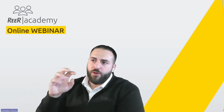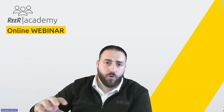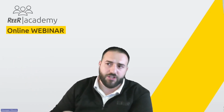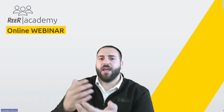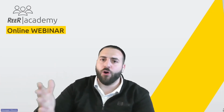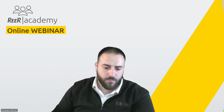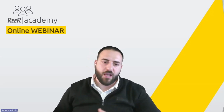So we don't need ProfiSafe because we don't need now to exchange data. Of course, we are planning to work on something that is able to communicate as a Profinet device with a ProfiSafe device at a higher level. But in this case, we cannot say it's the same. We collect all the safety functions into the module and send the monitoring data to a Profinet PLC, that is different from a ProfiSafe PLC.